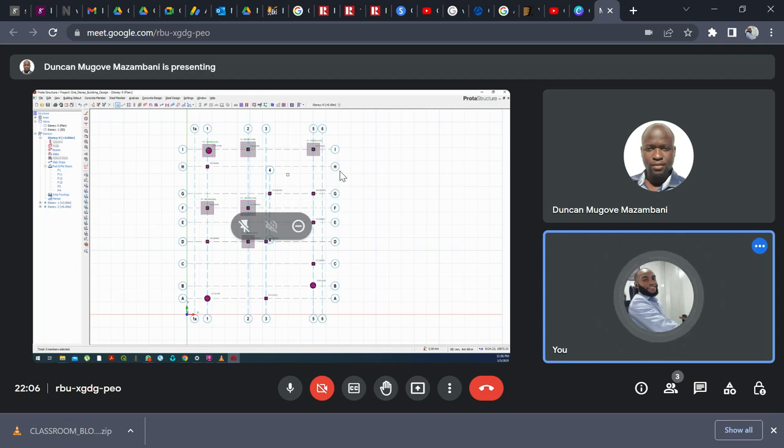So I'll send you a plan of a two-story building. Once I send you the plan, first of all, on the ground floor you have to do your GA, just as we did in the afternoon. On your ground floor GA, position your columns, panel it, and all that. Then copy your columns to the first floor, if the floors are the same, although they won't be the same, because I will send you a plan where the first floor, second floor and third floor are not the same.